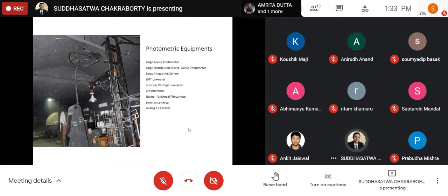But the problem is that here in our laboratory premises we don't have that much space, because you can't maintain this distance very high. So that's why we are using a mirror. The concept is that light will come from the source to the mirror and then it will reflect to the sensor. So my sensor is mounted at the bottommost portion of the baffle just to ensure that no direct light should reach from the luminaire to the sensor.